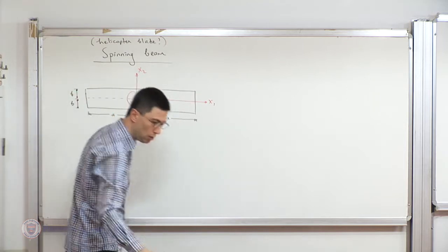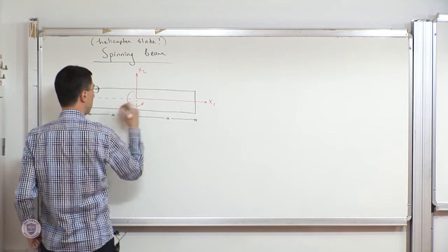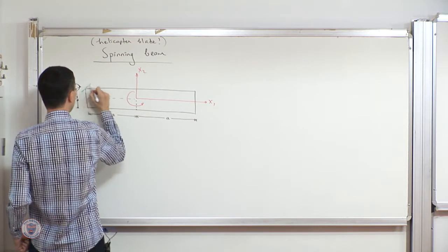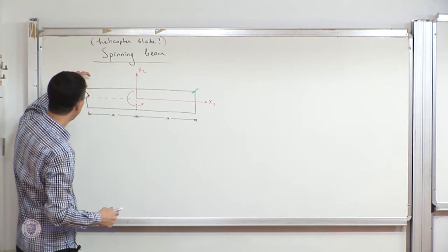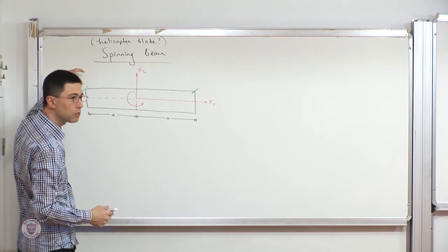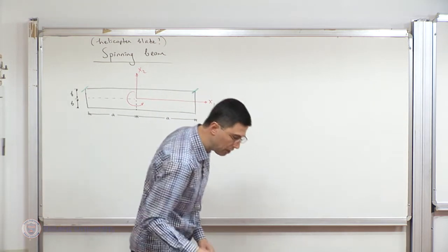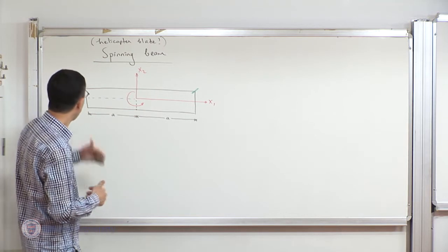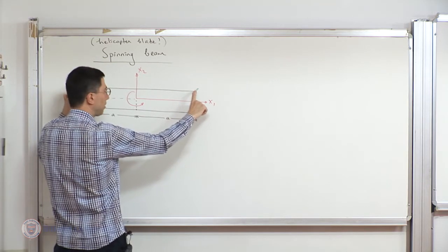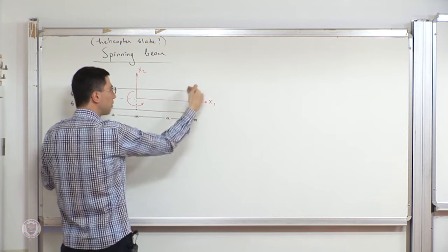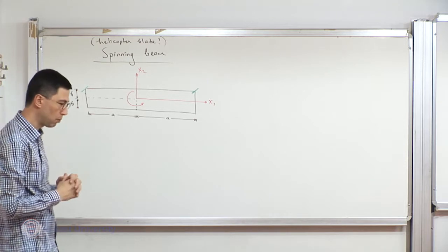So it's a rectangle. The thickness direction doesn't really matter because this could be a plane stress or strain case. If you like, this is the thickness direction. I don't want to complicate the drawing, okay? But it could be very thin, for instance, if it's plane stress, or it could be plane strain, and then we don't care about the thickness. Under those ideal scenarios, we're essentially taking a cut along the thickness direction, and this black rectangle indicates that cut. It really doesn't matter at which point along the thickness direction that cut is located if we're in an ideal plane strain or plane stress scenario.